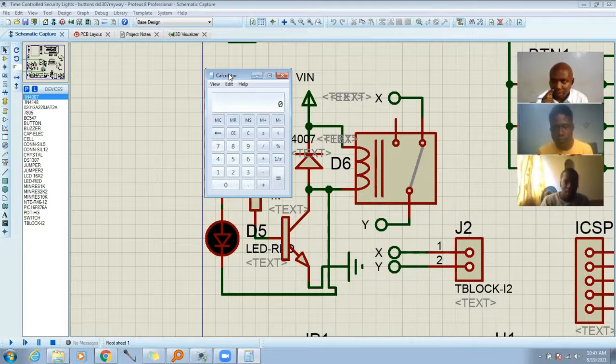Just divide. So what you need to do is just divide. We already know that this relay can stand 2,400, divided by your 100 watts. It means that you'll be able to connect 24 bulbs of 100 watts on that relay.